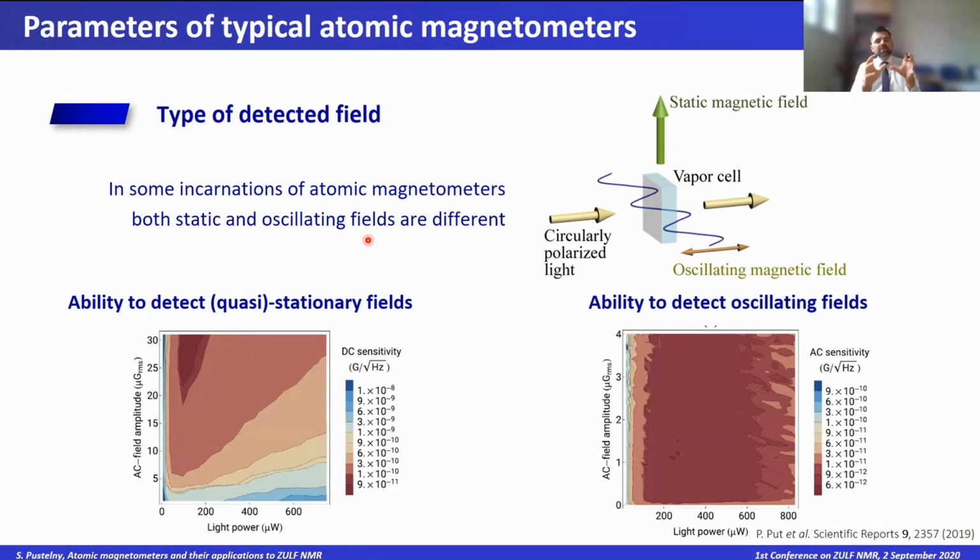So you can have your magnetometer measure the magnetic field, or you can have it work as a radio, where you tune the frequency so that you are exclusively sensitive to a specific frequency. This acts as a narrow band filter, and you can filter out the signal of interest. This is interesting in a situation when you want to detect some signal at higher frequencies.